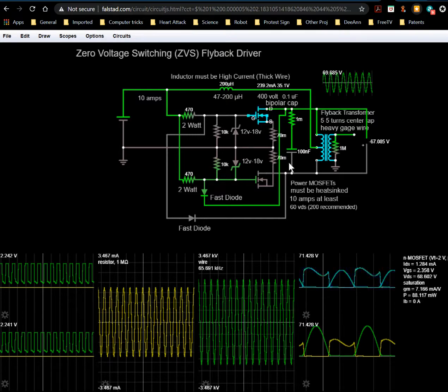So relative to this transistor, this has a voltage across it right now. Relative to this transistor, it has a voltage across it here, but a relatively low voltage here, and vice versa. So when one has low voltage across it, the other has high voltage. It has low voltage across it because its resistance is really low and it's conducting current.